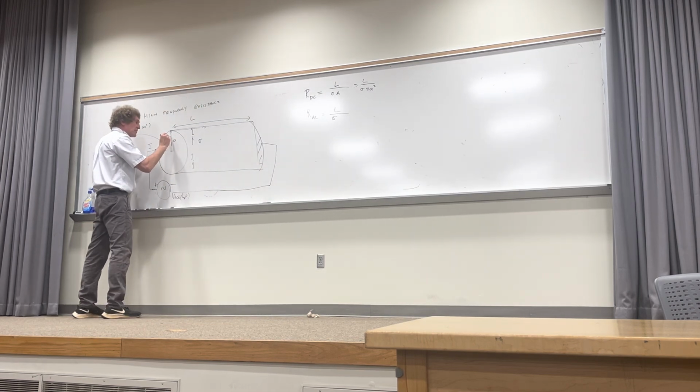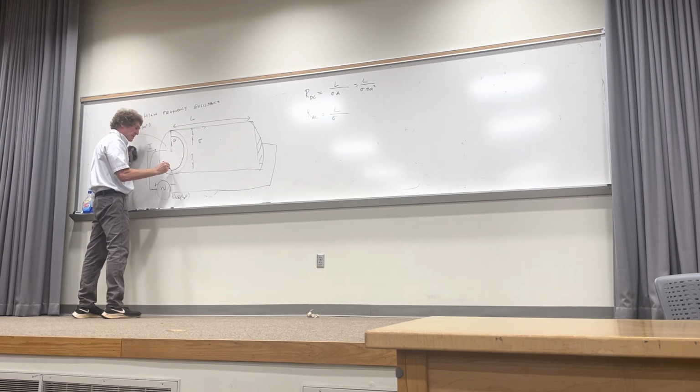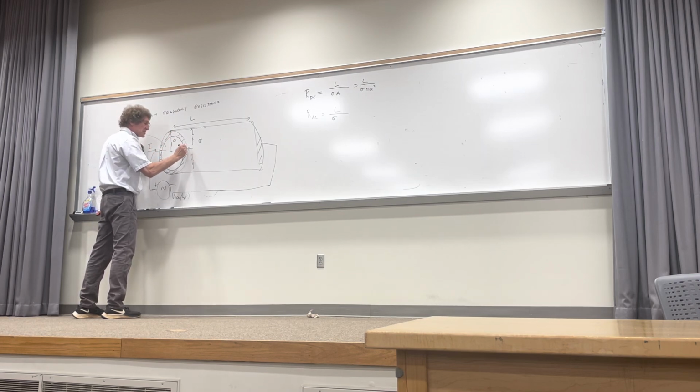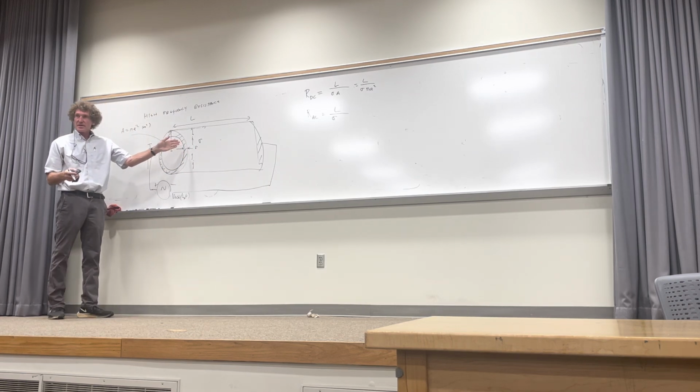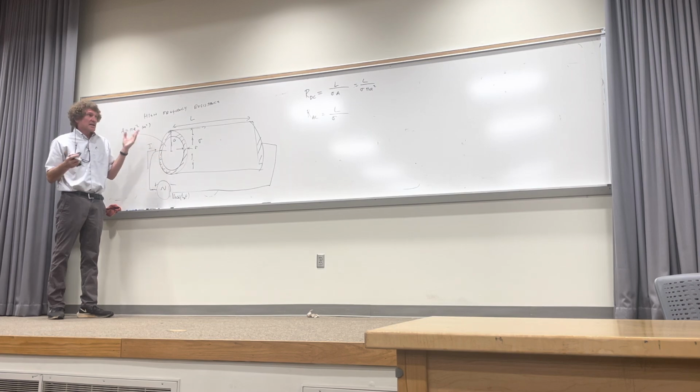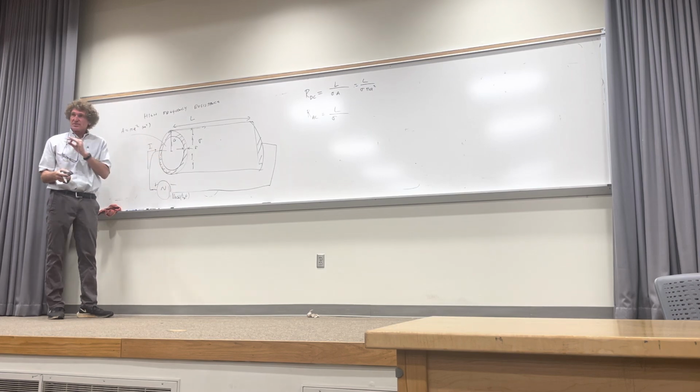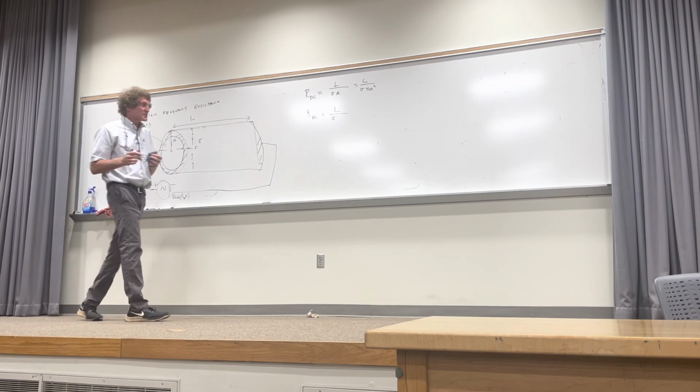The current will flow. It'll basically be trapped in one skin depth of the surface, all the current. Now you can prove this, you can actually write the equation and then integrate out the current density through the entire cross-section of the wire, and it comes down to this value. So this is not an approximation.